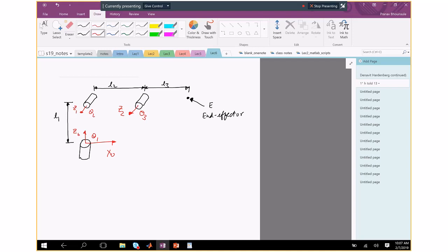which means, translating in this particular problem, X1 is going to be at right angles to Z0 and Z1. So Z0 is that way, Z1 is coming out of the plane of the paper. It has to be at right angles to that. So we need to find a vector which is always the tip of the pen is the direction of the axis. So Z0 is upwards, Z1 comes out of the plane, and X1 is going to be at right angles to